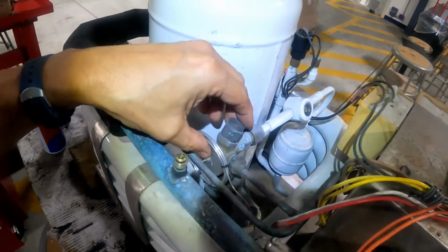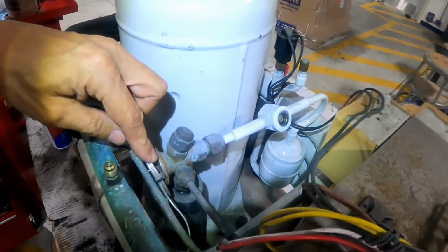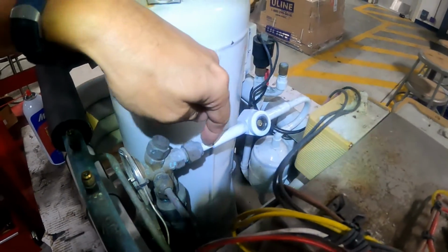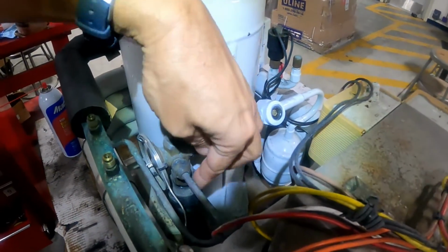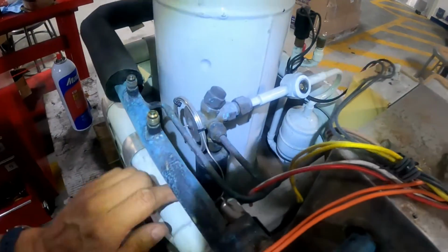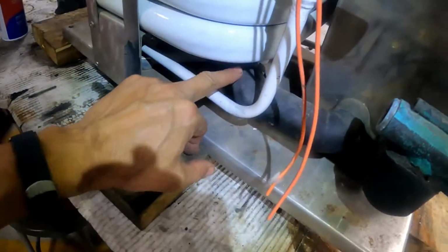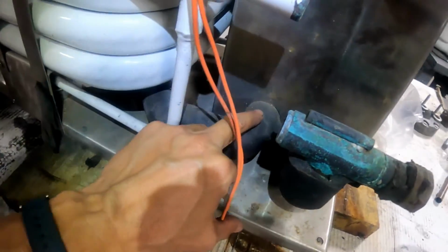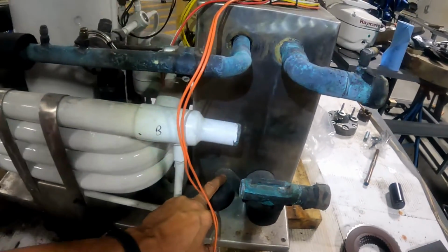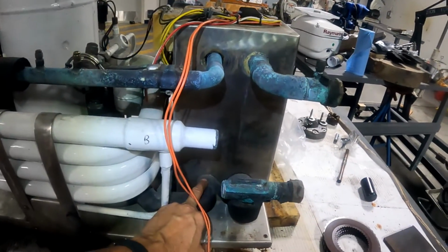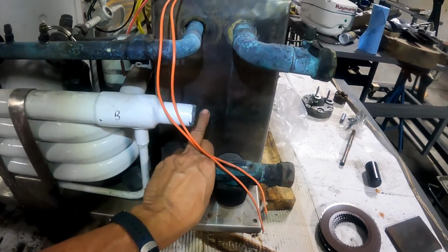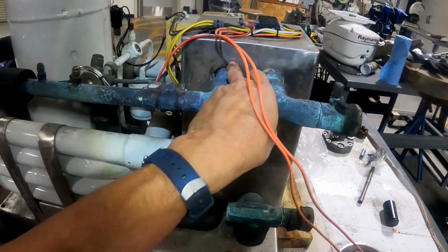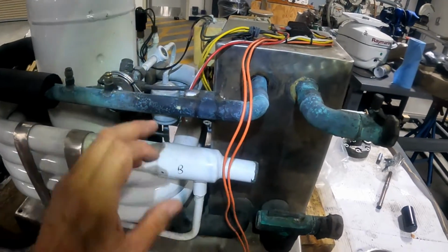the thermal expansion valve, and the thermal expansion valve opens and allows the fluid to pass through the venturi and produce the reduction in pressure and temperature, and goes down here with low pressure and low temperature and enters the bottom of this evaporator practically frozen, and continues frozen over there and returns here.